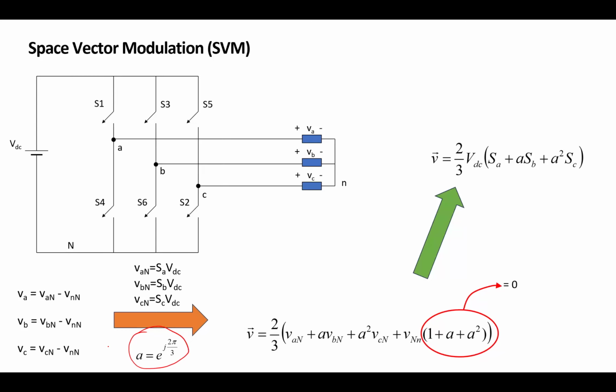So in three phase, we know that we have three voltages that are shifted 120 degrees from each other. So if the voltage A has theta equal to 0, phase B is minus 120, phase C is plus 120. 120 phase shift from each other. Make sense? We have three phases. So how could we describe that?